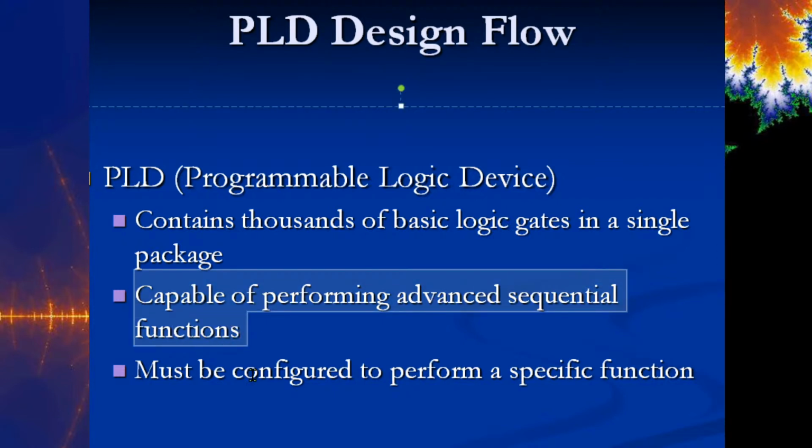So instead of having to wire up an incredibly complex circuit, maybe using 14 or 15 IC chips, okay? That's a lot of wiring that could go awry, all right? So if you have it all laid out in something like this, just to try to test it out, because if you're going to try to test it by actually physically building it, you could waste half of your time troubleshooting. Now, that may happen anyway, but you at least want to be trying to achieve a design that you know is good, that simulates good, that has been proven in the software, okay?